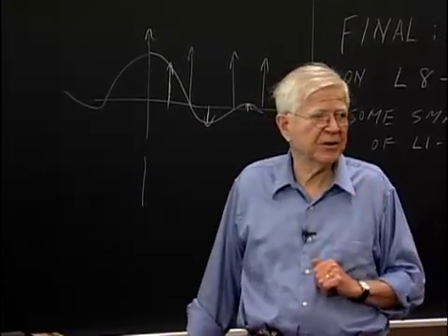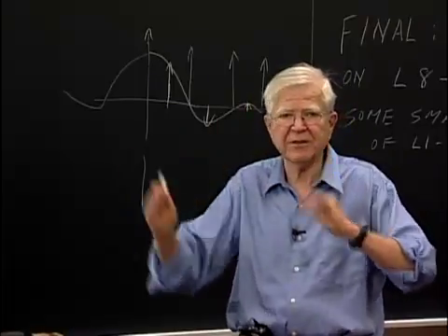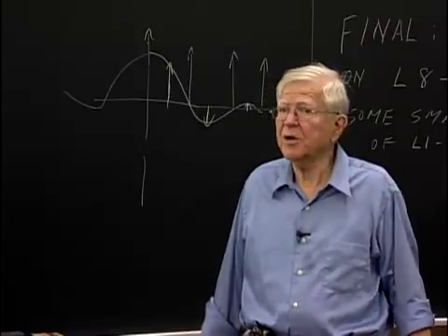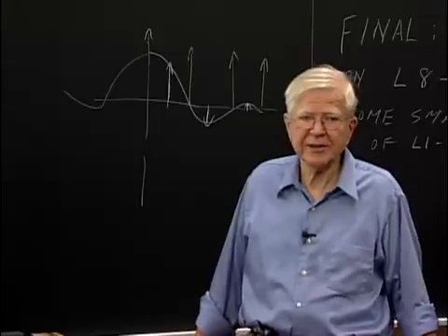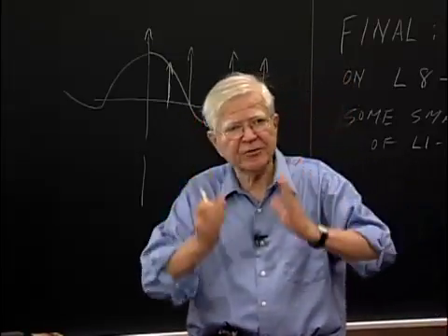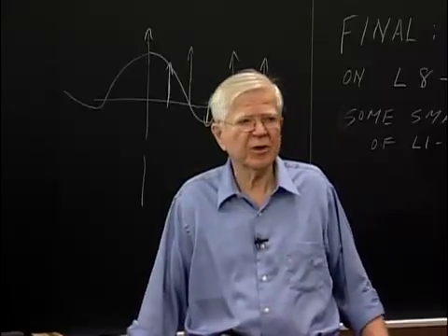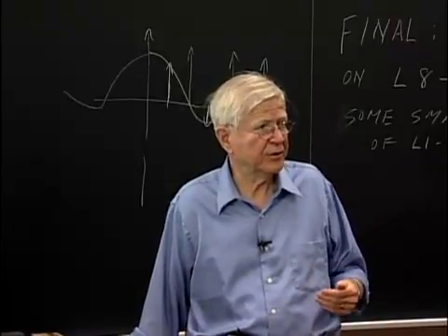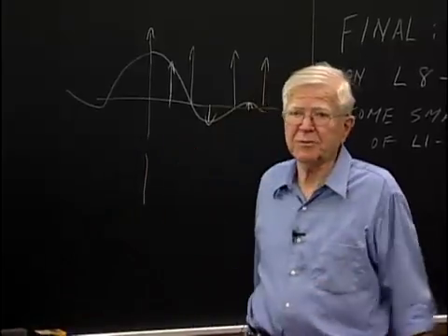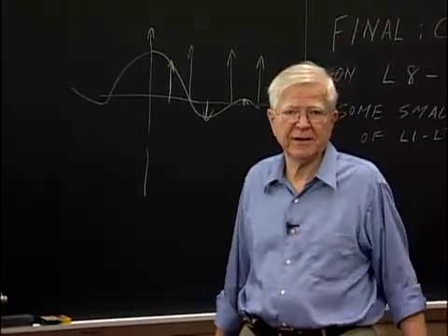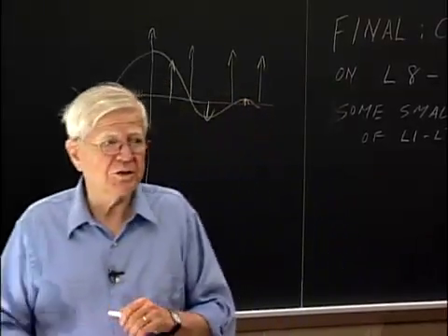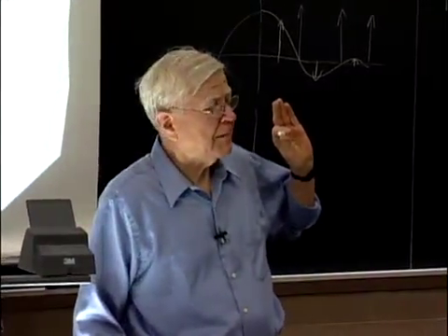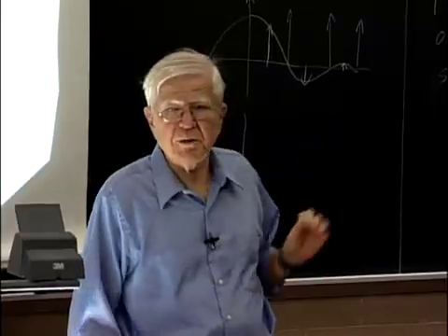Now when you use the analog filter and you actually put these taps of the rake receiver at the places where you have actual physical responses, you do much, much better. And you particularly do better if the impulse response duration of the channel is of the same order of magnitude as 1 over the bandwidth of the source that you're using. Because at that point, this becomes an important issue. That's exactly the situation we have here, because the impulse response of these channels, 1 over the bandwidth of the input,